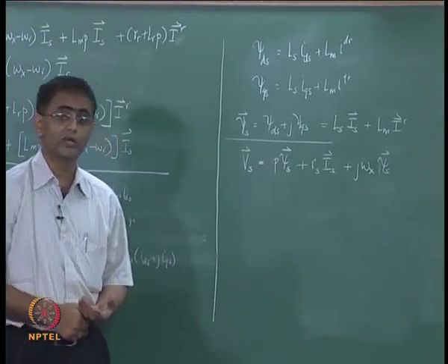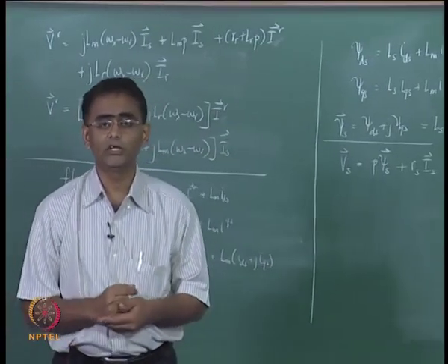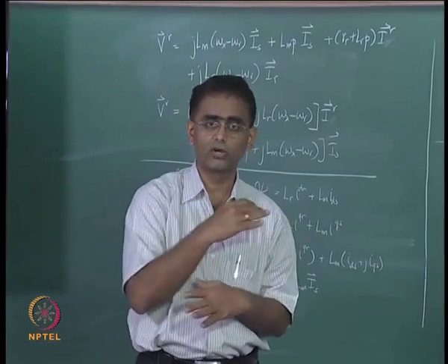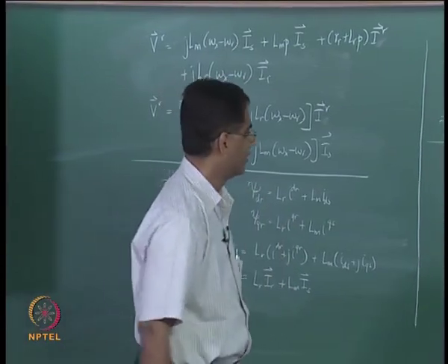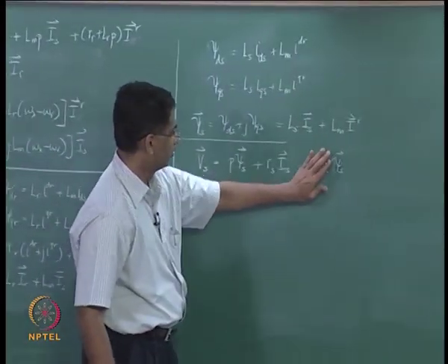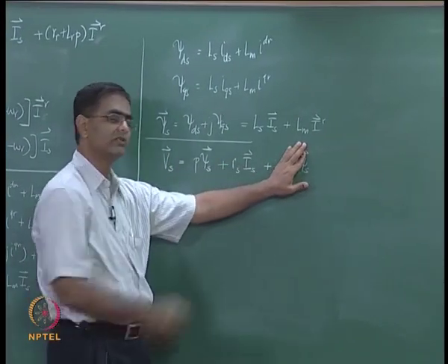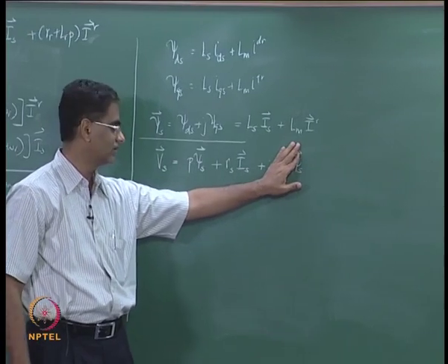Suppose you are looking at the description of the machine in the stator attached reference frame, that means the reference frame is not rotating, it is at 0 speed, then omega x is 0, then this term is not there, and this equation now looks like a very familiar equation.